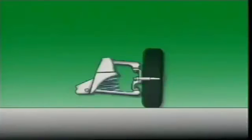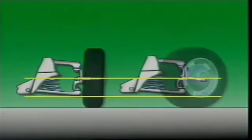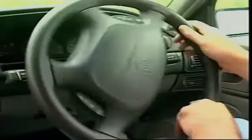Steering axis inclination acts with caster to provide a self-centering of the front wheels. When the wheels are in the straight ahead position, the ends of the stub axles are almost horizontal. When the wheels turn to either side, the effective steering axis inclination is to make the ends of the stub axle tend to move downward, but this is prevented by the wheel. The stub axle carrier then must move up, which raises the front of the vehicle. When the steering wheel is released, the mass of the vehicle forces the stub carrier back down, which pushes the wheels back to a central position.